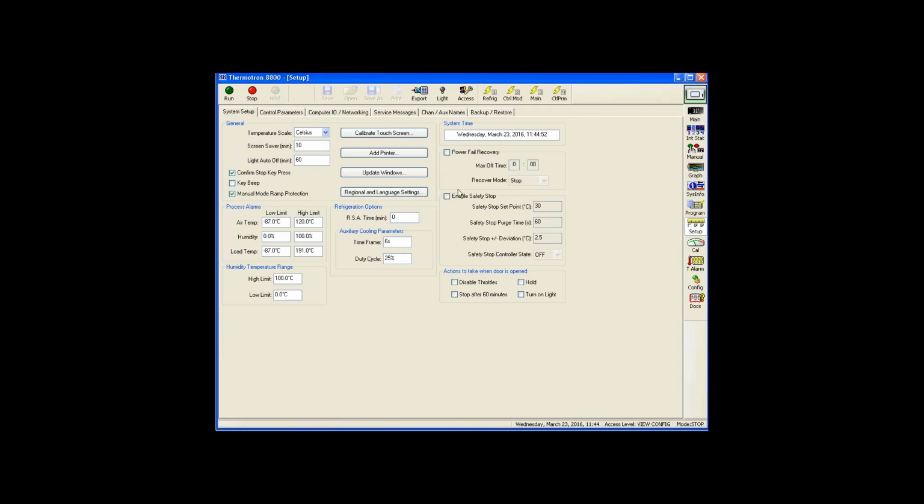There's a safety stop that we built into the software, and this was something for a particular customer. They were having issues with, they would be at a cold temperature profile, and the users were instructed if a product fails during test, go in and pull it out. And what was happening is they would open up the door, it'd be -60 degrees, they'd get a bunch of condensation on all the products. So what they wanted was a way to, when the user hit stop, instead of stopping and allowing them to open up the door, it would first go to a safe temperature and then allow them to open up the door.